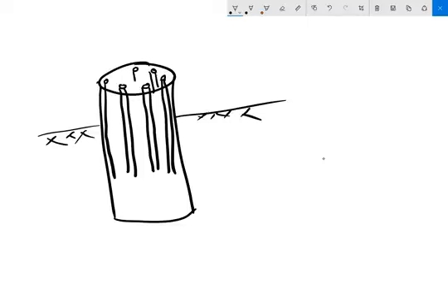So anyway, you get the idea. So this shaft is built with concrete. The concrete cures and everything's fine. And what we do then is we'll stick our receiver down there. We'll stick our seismic source down there. And we'll go ahead and do crosshole testing all the way down the drilled shaft.